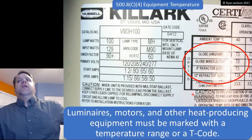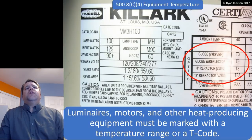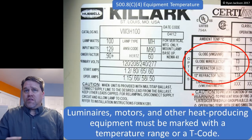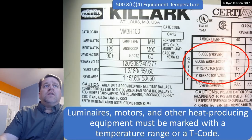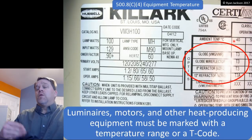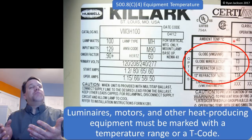This is something that I've found a lot of people in the industry don't know about, and that's temperature, or T-code, ratings. Luminaires, motors, and other heat-producing equipment must be marked with a temperature range, or a T-code. Okay, here we have a luminaire, and in an ambient temperature of 40 degrees C, now 40 degrees C happens to be one of the few Celsius measurements that I know. 40 degrees C is 104 F. So let's just say room temperature.